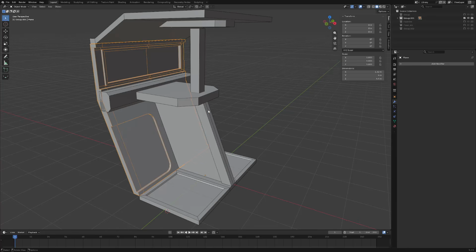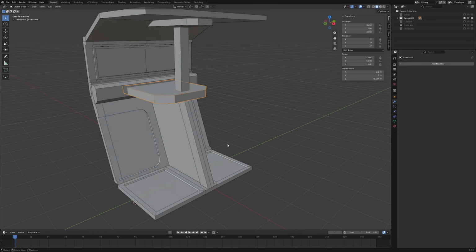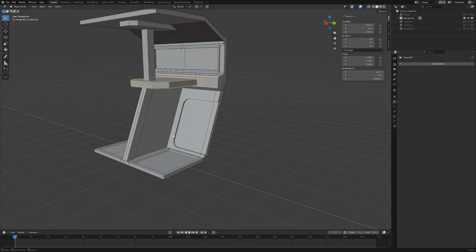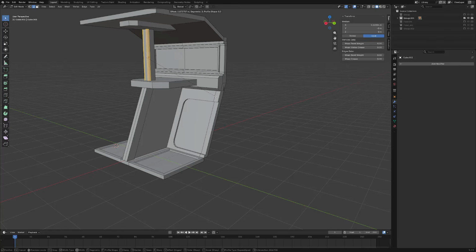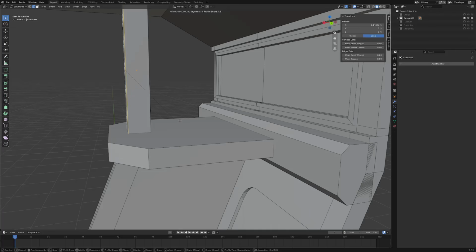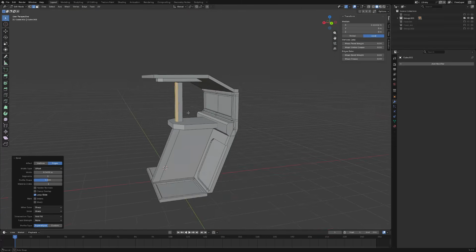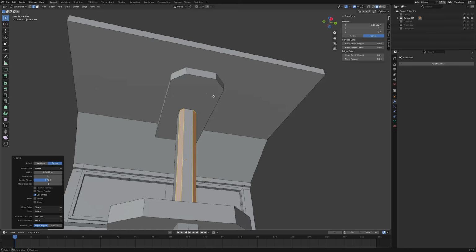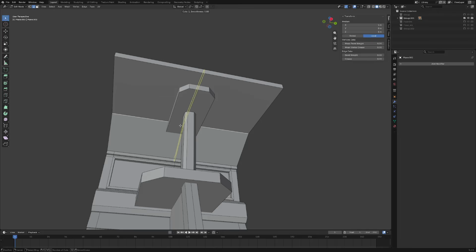I want it solid right now because I'm going to do some booleans here in a second with the manifold boolean solver. But basically you can see we can come in, we can start detailing, we can make all kinds of fun things happen here if we really wanted to. It's a really good overall process of working with groups. It's something that Blender desperately needs to add as a vanilla feature, but they haven't done it yet. So maybe we do a couple cuts into here. I'm going to inset, grab, Shift R, R.